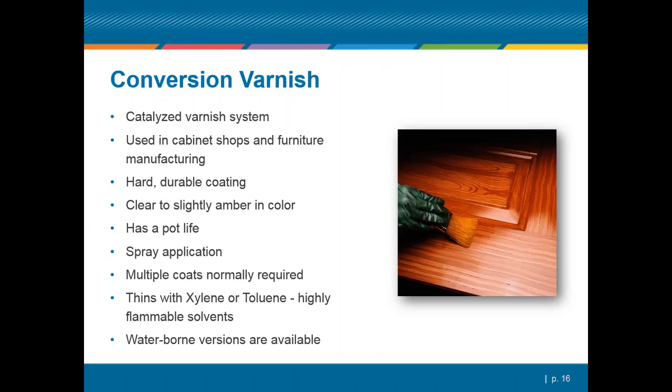Multiple coats are normally required. Again, they're relatively fast dry, so you can put multiple coats on in a day. Xylene and toluene, both of those solvents, are highly flammable, and they do have an odor to them also. So if we're trying to use any of these finishes on site, in a new construction situation it may not be as detrimental as in an occupied space.